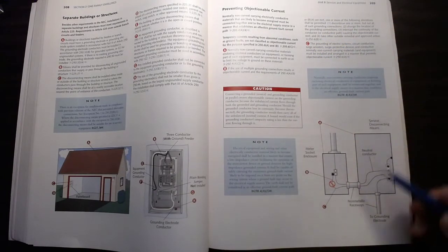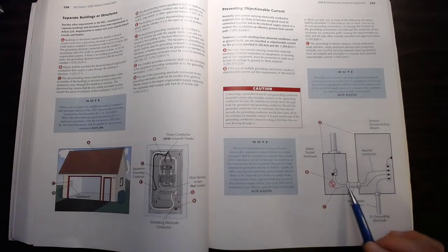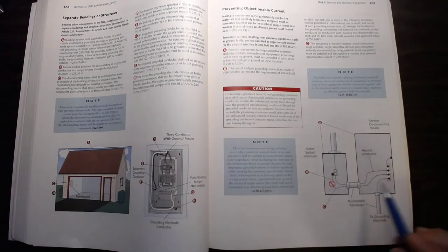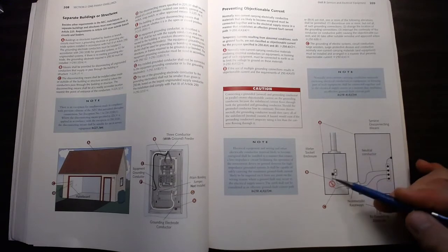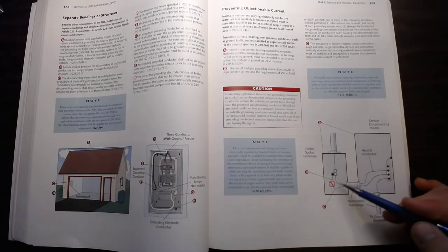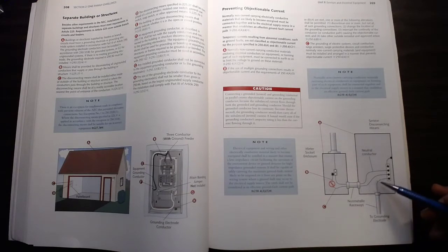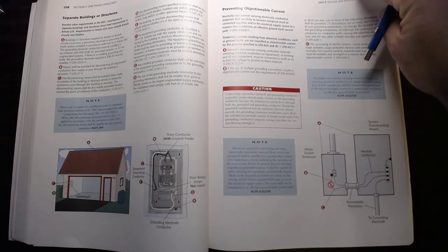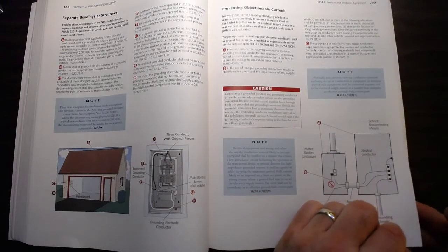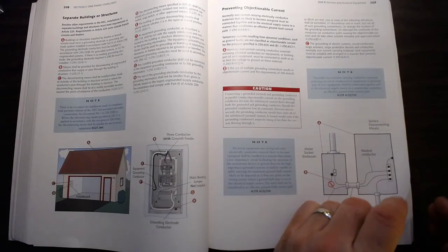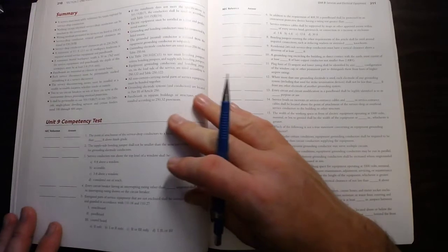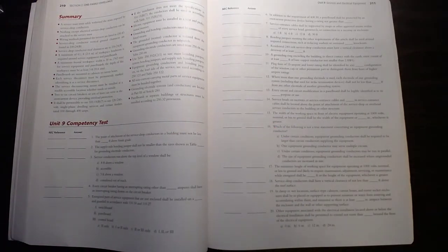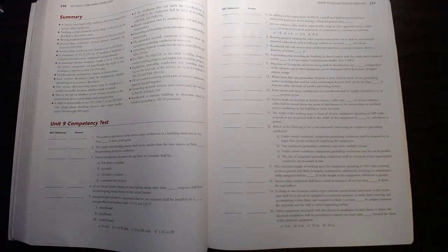So, for example, you've put in multiple neutral to ground bonds. You've bonded it here in this enclosure, and you bonded it in this enclosure, and now you can have current flowing across parallel paths, and you could have it going across the metal of the enclosure, and that is not where we want it to flow. So we want to make sure that we are bonded to neutral only at the service or at the service disconnecting location. So that was a very fast run through of grounding.